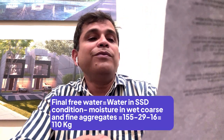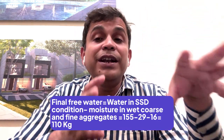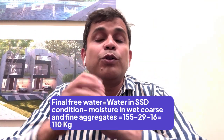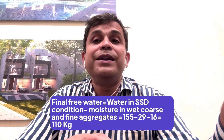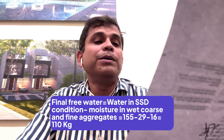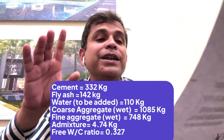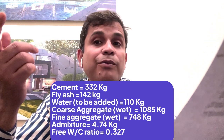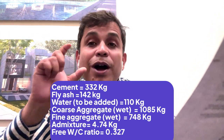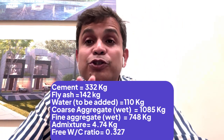So from these 155 kgs, we need to deduct the water we are getting from the coarse aggregate and fine aggregate, that is 45 kgs. If we deduct that, the revised mix will be: cement 332 kgs, coarse aggregate 1085 kgs, fine aggregate 748 kgs, and water 155 minus 45, that is 110 kgs. But the water cement ratio will be the same.